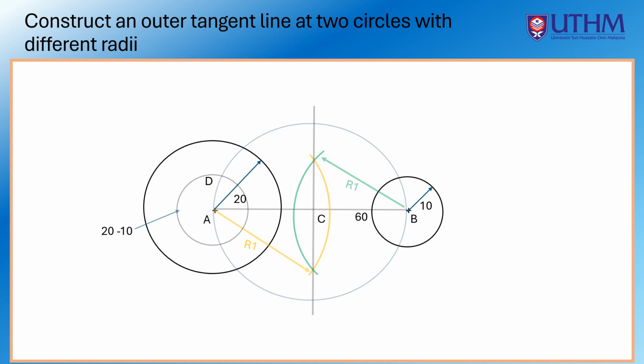Then create a straight line from point A to D and to E. That is the point E. At point B, draw a straight line that is parallel to line ADE to create a BF line. That is the F point. Finally, draw a tangent line that passes through point E and F. That is the tangent line that you need.